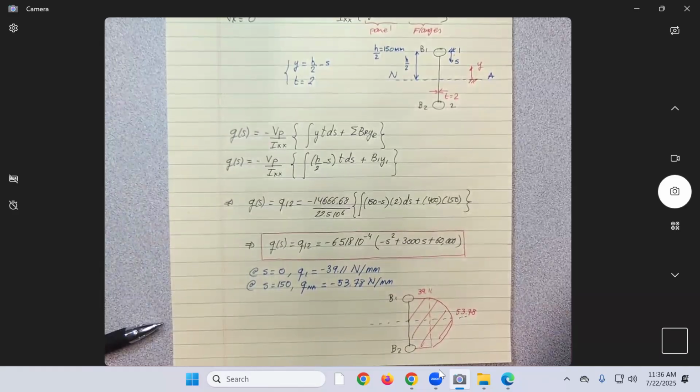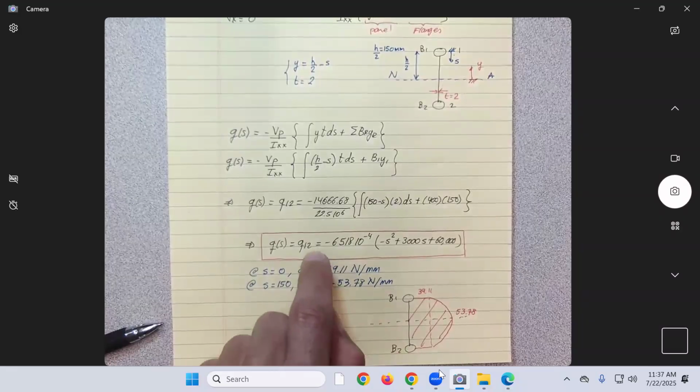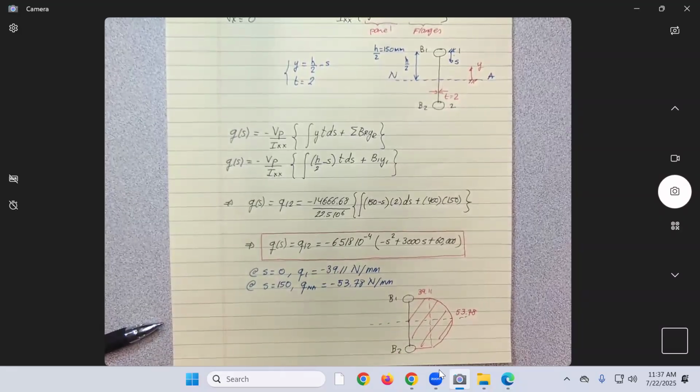And basically, we do the top and the lower part will be by symmetry. We did not assume Ixy is 0, so we know it's symmetric. If you want, you can redo the same thing as you did in the assignment. You can go from the neutral axis to Q2 and redo the calculation. In this case, I just did it a bit faster, okay?